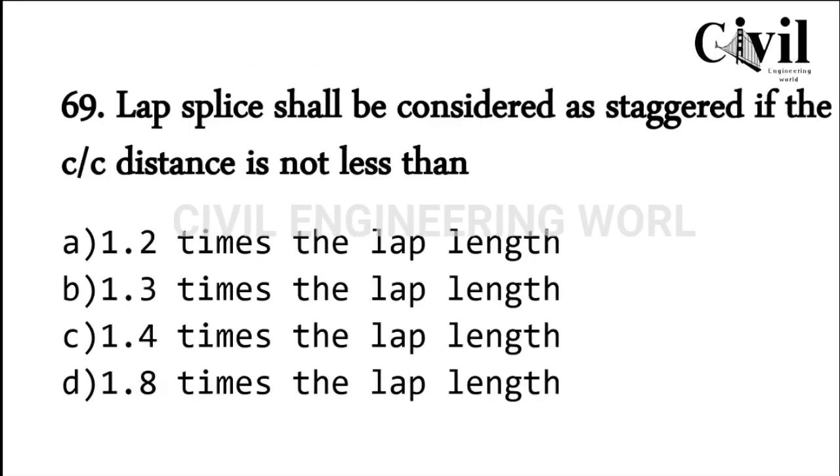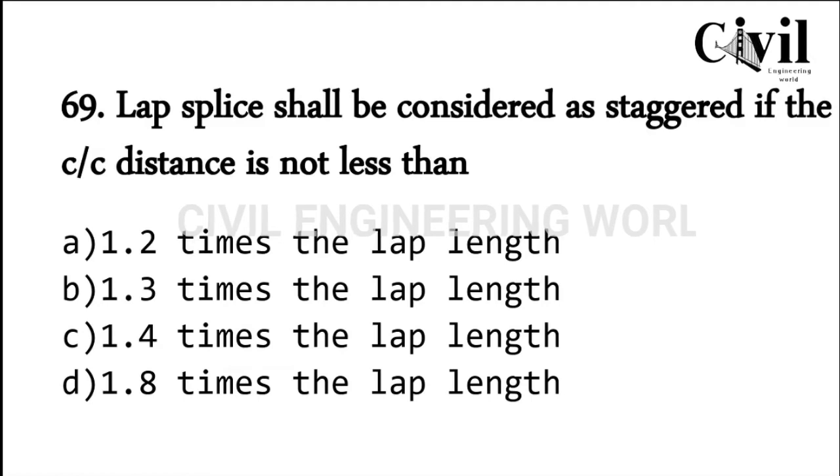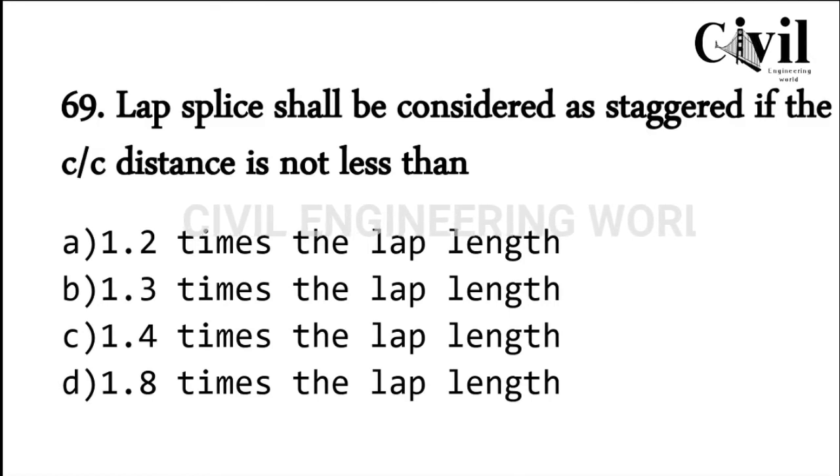Lap splice shall be considered as staggered if the center to center distance is not less than. So if it is not less than 1.3 times lap length, then it means that lap splice is considered as staggered. So here B will be the correct answer.